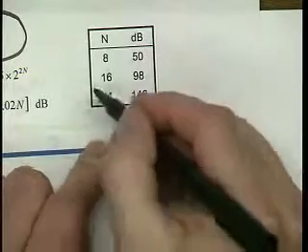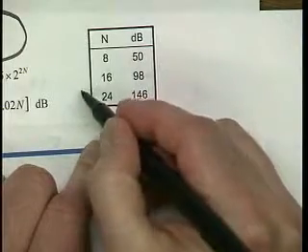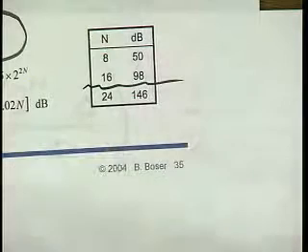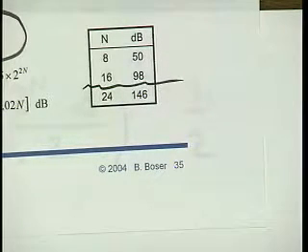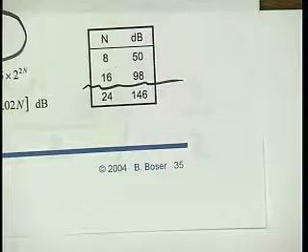Now, if you looked at data sheets for audio equipment or so, then stuff tops out around 100 dB or so. So analog circuits, the good ones, get into the 16-bit equivalent signal-to-noise ratio range, and far beyond that is hard, and 8 bits, sort of 50 dB, isn't that big a deal.